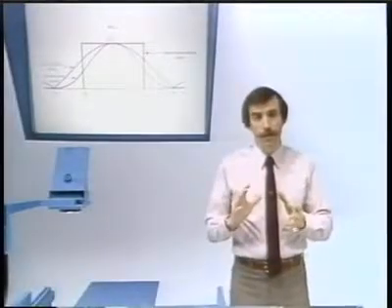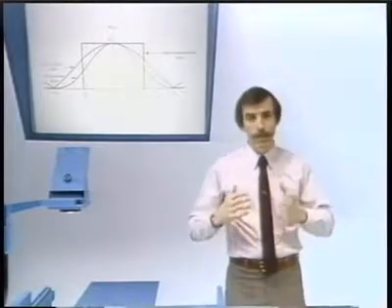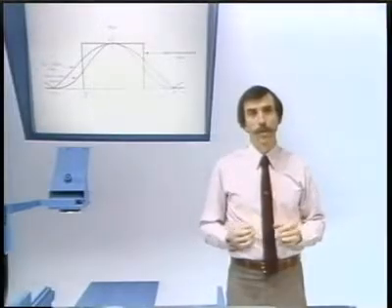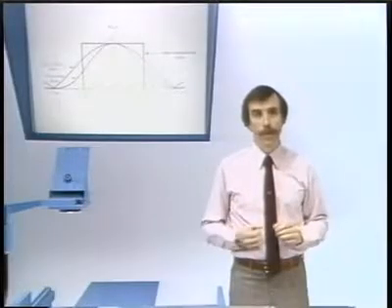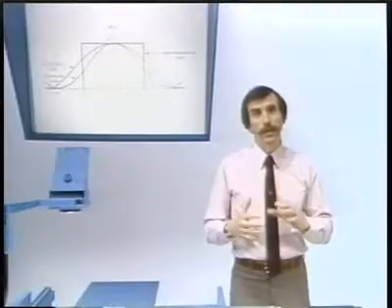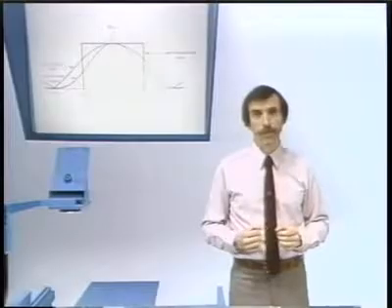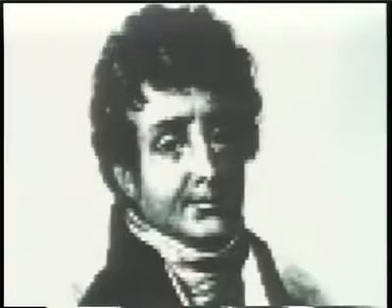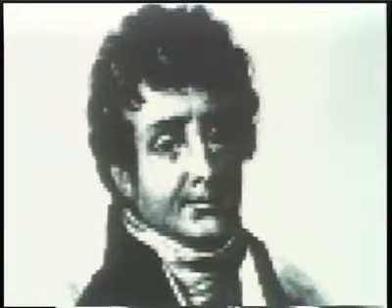Now, these images are, in fact, taken off a computer display, and a common procedure in computer-generated or displayed images is the use of a zero-order hold. And if the sampling rate is high enough, then that actually works reasonably well. So now let's look at the result of applying a zero-order hold to the sampled image that I just showed. The zero-order hold corresponds to replacing the impulses by rectangles, and you can see that what that generates is a mosaic effect, as you would expect.